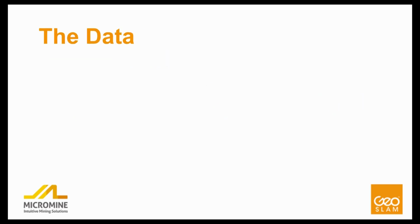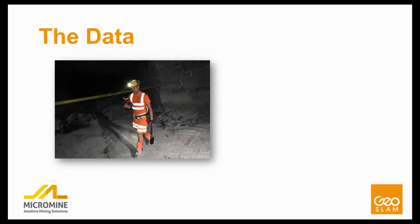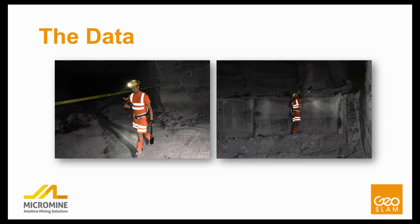But in a mine, how does this work? It's literally as I described it. You turn the scanner on, you walk through an environment, and it captures that whole area for you. So imagine how traditional methods, you set up the tripod, you take the scan 360, you take down the tripod, you move to the next position. You literally walk through the environment and it captures it for you using SLAM.